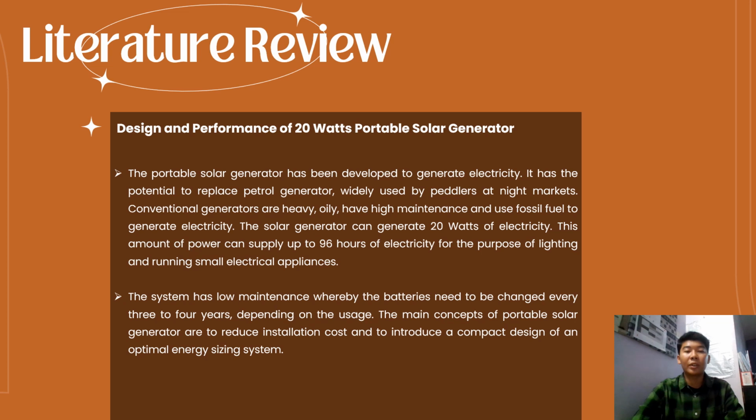And last, for the research of design and performance of a 20 watts portable solar generator. The portable solar generator has been developed to generate electricity. It has the potential to replace the petrol generator widely used by peddlers at night markets. The system also has low maintenance, whereby the batteries need to be changed every 3 or 4 years, depending on the usage. The main concept of the portable solar generator is to reduce installation costs and to introduce a compact design of an optimal energy sizing system.